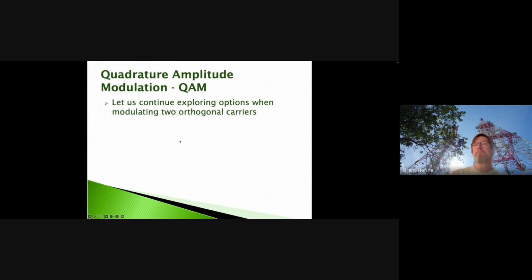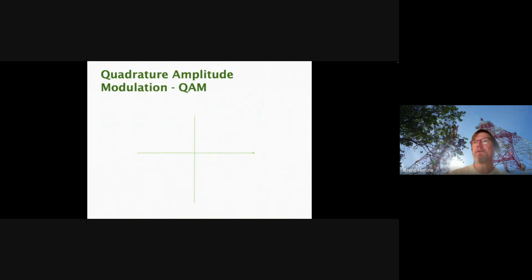So we already kind of covered this. Now let's look at QAM. So in PAM, we were all aligned on this real axis, right? And now we're going to space it on both the real and imaginary axis, or in the complex plane. Again, we kind of like this idea of balancing things about 0, so that overall, maybe sometimes we've got some negative voltage, some positive voltage, but on average they're going to kind of cancel out.